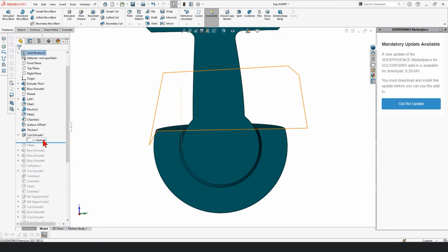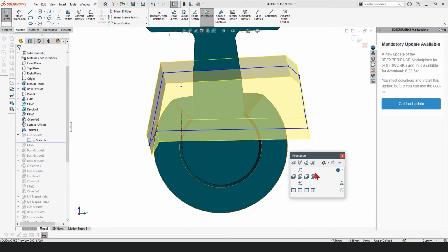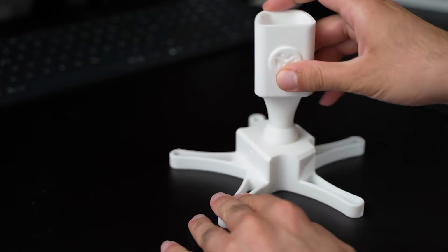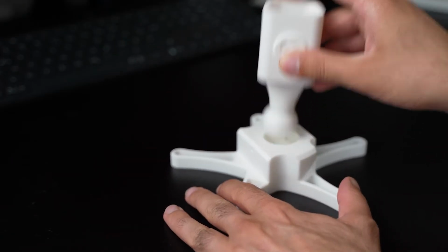Because yes, if you get your ball already installed inside the joint, even that design would work, although your maneuverability is much limited because of the opening you have here. But it doesn't come already assembled. You have to assemble them together. And if you make the hole too big, then the ball would not stay in the joint. It would just pop out. It's too loose. If you make the opening too small, you cannot even assemble them. So you have to find that perfect opening.